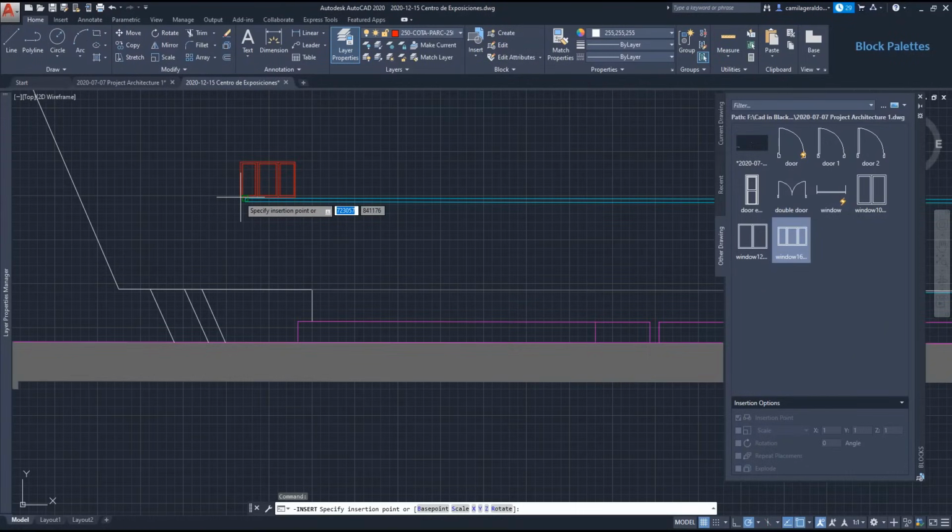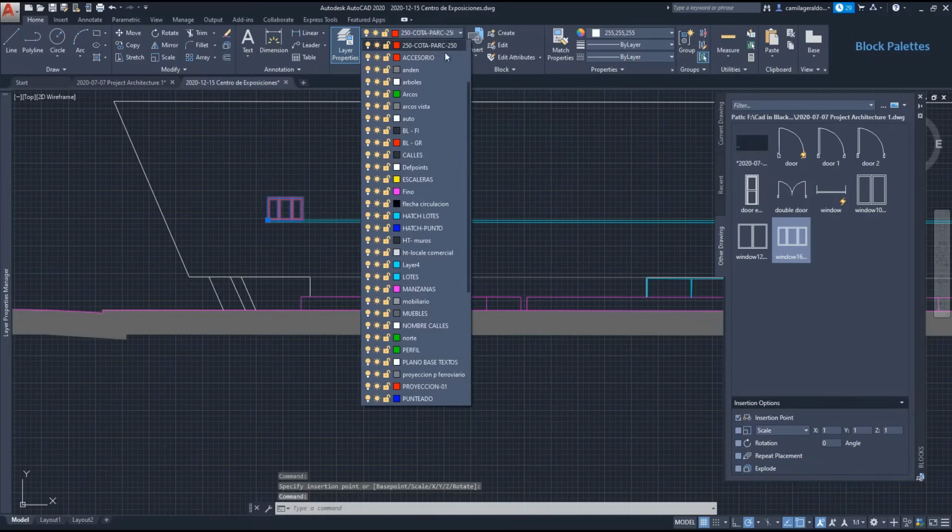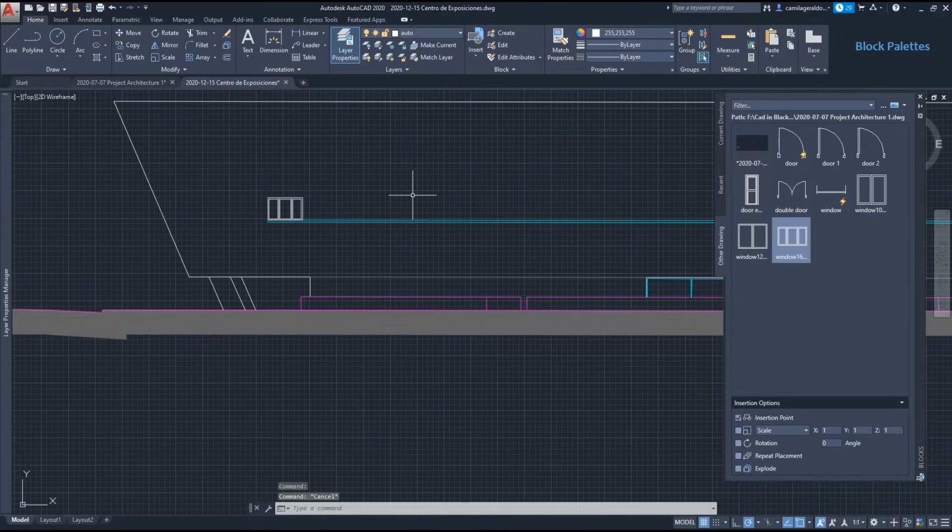You can see here that is the only option ticked. The disadvantage regarding the design center is that I cannot see the unit in which the block was created. Anyway, I don't think that's a big issue, as I can always check it on its properties, and if you notice that it's not the right size when you insert a block, you can simply apply a scale to it.